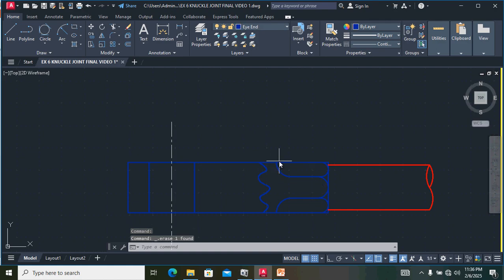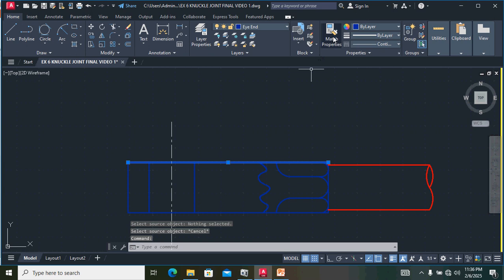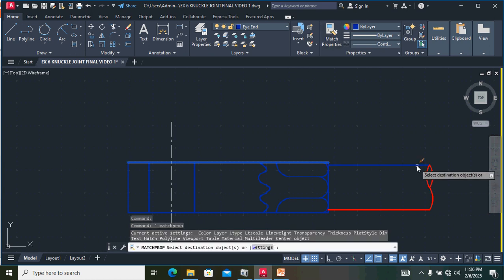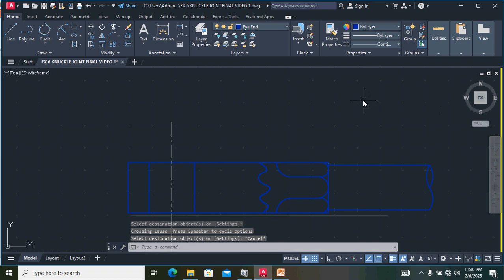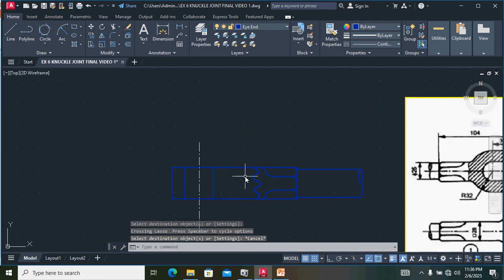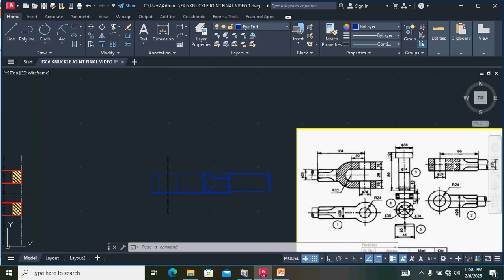Here, we have to take a mirror in this component. Select this point and take the mirror, from this point to this point. With ortho mode on, in this shape we have to draw in the downward direction and click enter. Okay, just enter.